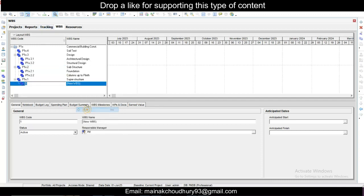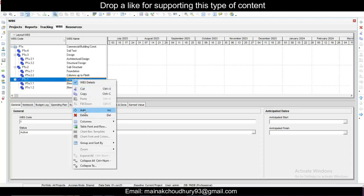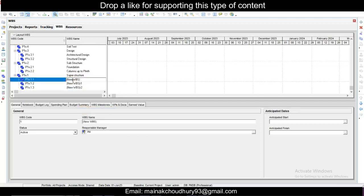Right click and click on add, right click, click on add. For the various members we can add these things, so for example, start from the plinth beam, then columns up to first slab or the first roof, and then you have ground floor slab, ground floor roof slab.